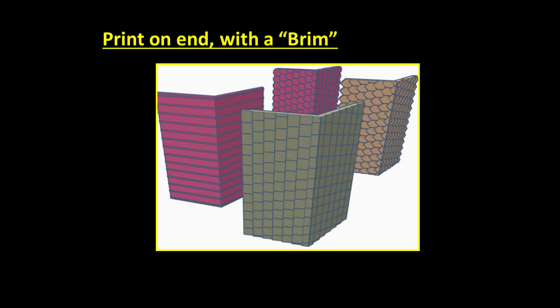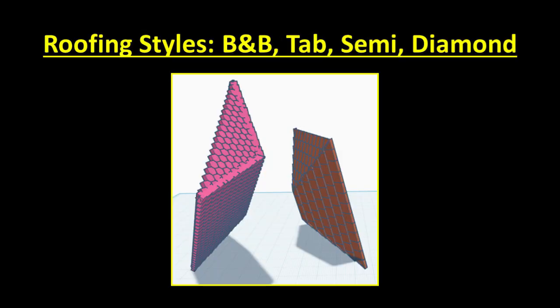I show these simple roofs standing on edge because I find they print better on my Bambu P1S printer that way. But for hipped roofs, I print them standing on a corner and use slicer-generated supports because doing so minimizes the amount of support material used and makes it easier to remove the supports after printing.